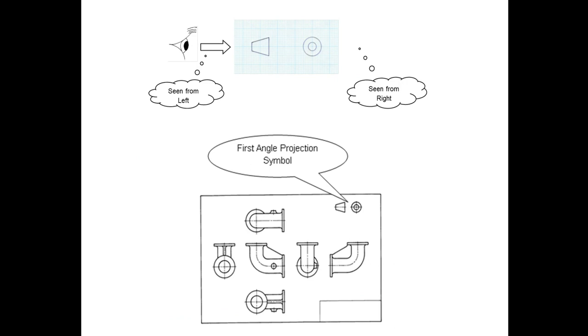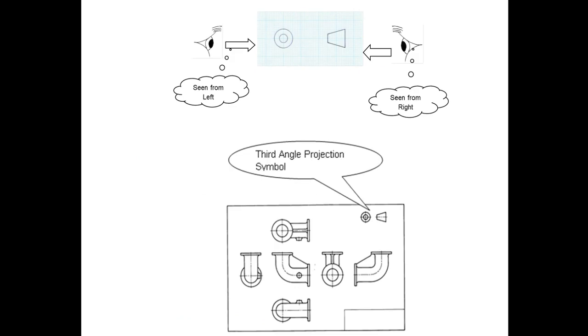When we work with drawings, we continue to work using international standards and conforming to international needs. So we can either produce drawings using first angle or third angle. We're going to work mainly in third angle, so we'll have a little recap of that as we go through doing some drawings. In third angle projection, we need to make sure we put the symbols in and we conform. Any views that aren't conforming to a standard projection, first or third, we need to put arrows in and note the way in which we're looking at them. We'll add notes to the drawing.